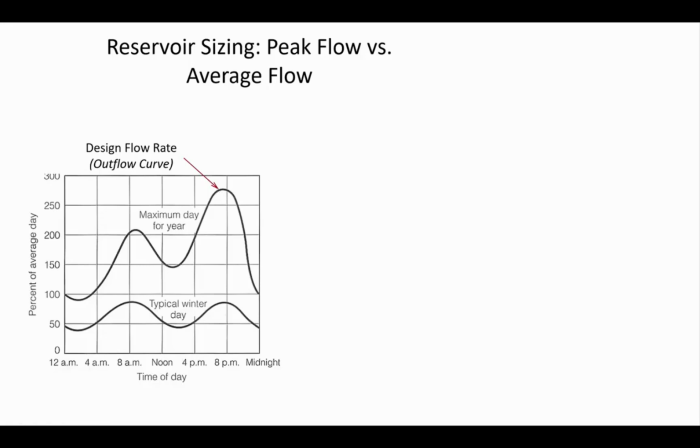And we know from your demand estimation summary sheet, at the very bottom of that summary page I asked you to write all your numbers on, it says what's the demand for the whole network. And we're saying, by definition, we're going to tie this curve to that peak. So it maybe is 200 liters per second for your city, or maybe somebody else's city is 300 liters per second, or 350 or 400. Everybody had different assumptions that were assigned for the project, and so everyone's going to have a different maximum outflow for the network.